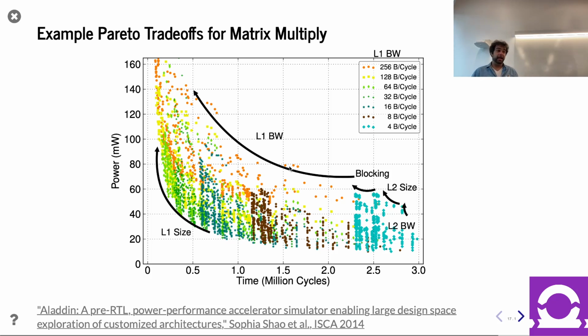So in this particular paper, actually very fast. This is the research now, which, oh my gosh, I'm dating myself. As you can see, it's 10 years old. And so the contribution of this research paper, which is called Aladdin, was to characterize a technology. So in other words, you have your PDKs, you have your ASIC CAD flow. It would run a variety of designs through it, look at how much area and power that took, and then it would try other design variants, and using that model, compute the area and power without actually doing a full synthesis and place and route.